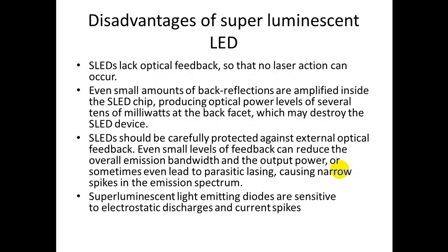Now let us see disadvantages of superluminescent LED. SLEDs lack optical feedback so that no laser action can occur. Even small amounts of back reflections are amplified inside the SLED chip, producing optical power levels of several tens of milliwatts at the back facet, which may destroy the SLED device. SLEDs should be carefully protected against external optical feedback. Superluminescent light emitting diodes are sensitive to electrostatic discharges and current spikes.